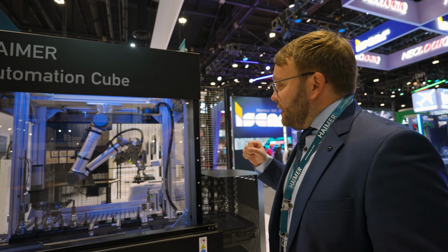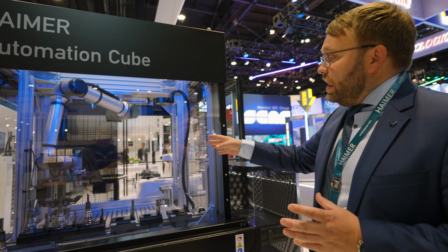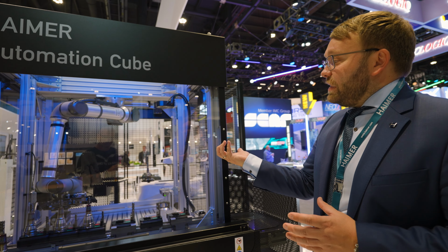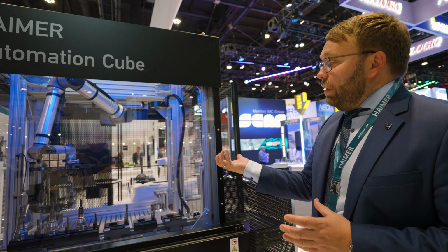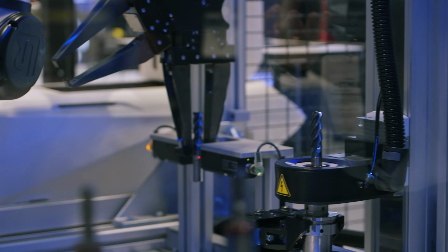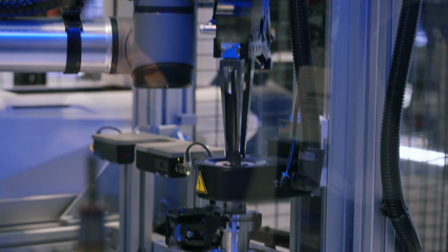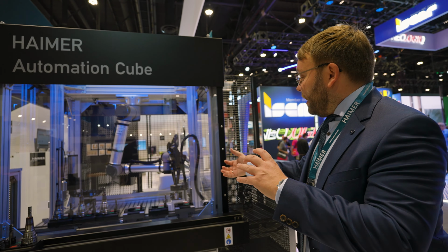So it takes the old cutting tool out and puts it on the cooling station. When it's on the cooling station, it rotates so that the cooled-down holder will then be put on the presetting machine. The robot automatically takes out the cutting tool and puts in the new cutting tool. It knows the stick-out length, then starts shrinking, takes out the old cutting tool and inserts the new one.